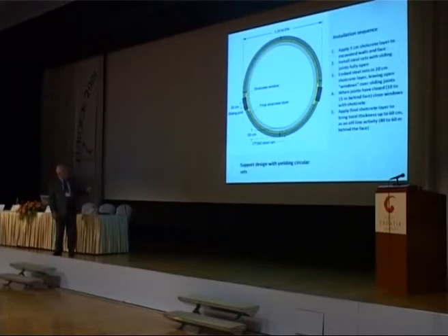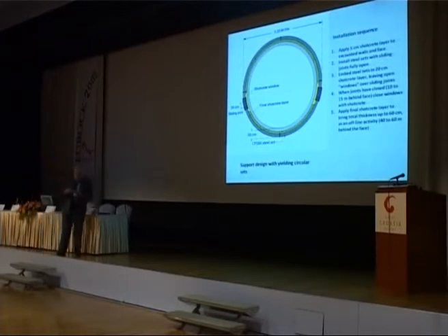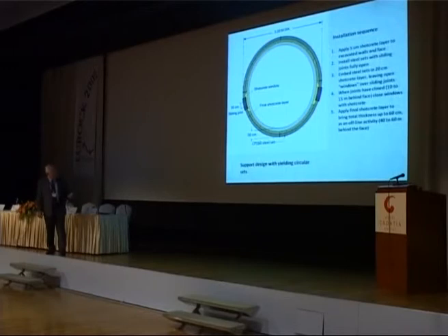These are embedded in shotcrete, except for a window of about 1 meter width, which is left open until the tunnel has advanced about 15 meters, at which stage either the sets have butted together and locked, or you close the tunnel with shotcrete. And then a final layer of shotcrete goes on the inside to give you the total lining, which for most of the tunnel was 60 centimeters of shotcrete.